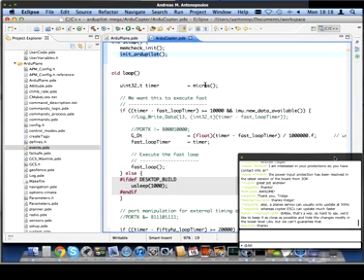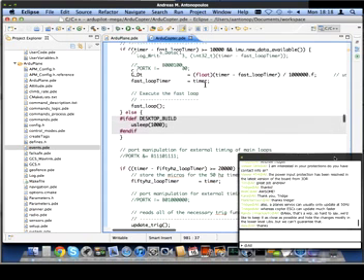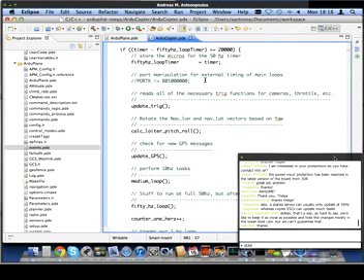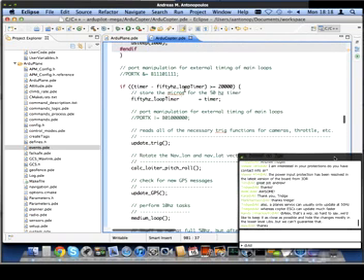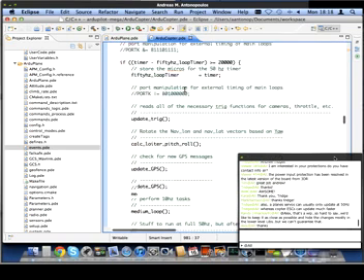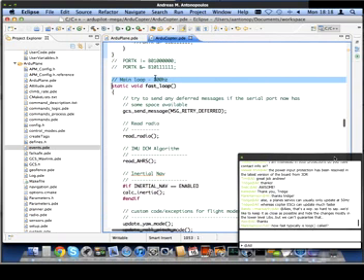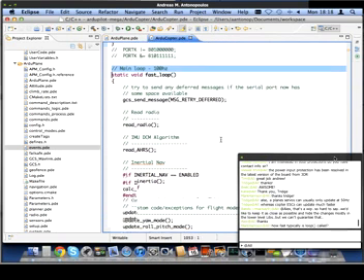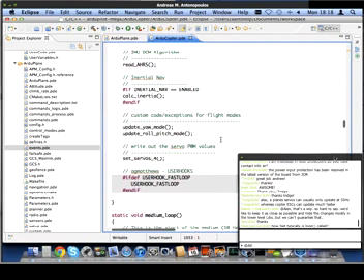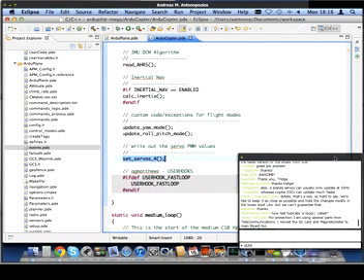All right, once again, as you can see, the timers use interrupt, so this loop is called basically as frequently as possible. One of the differences you see in ArduCopter versus ArduPlane is that rather than using milliseconds, the timers are actually based on microseconds because we want to be able to have some fine-grained control. Here, the 50 hertz timer is actually a slow timer compared to the super fast loop, which we want to run at 100 hertz or more.